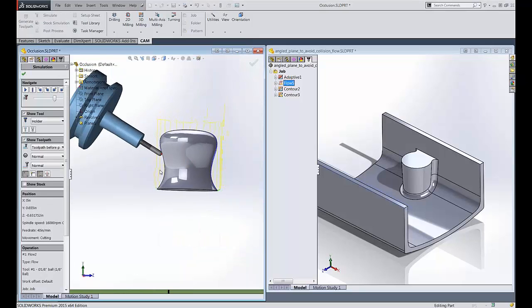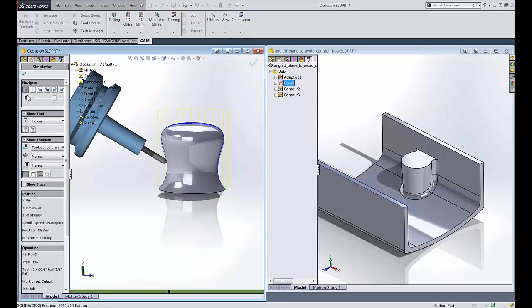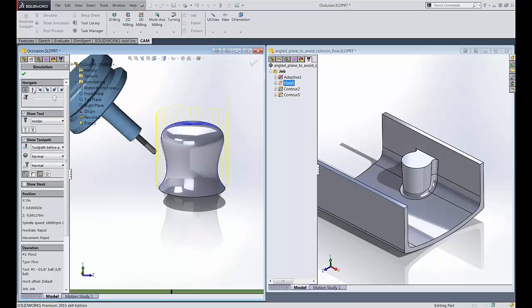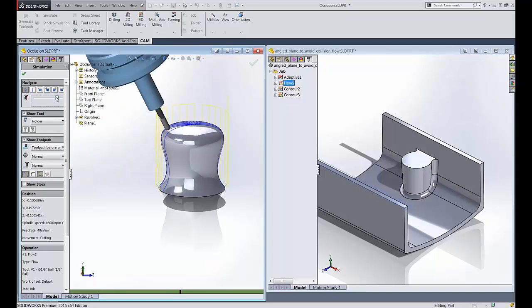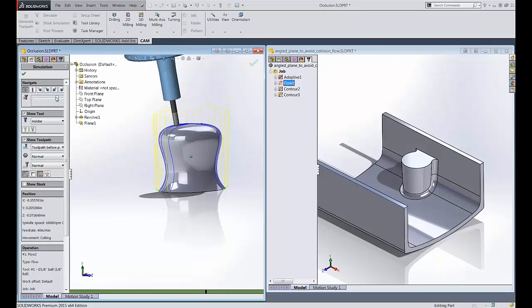Yeah, like I said, it's way more than we need. But it gets the tangency, the shank of the tool or the flute of the tool, out of the way so we can continue surfacing. And you'll see it's able to cover the entire surface with a single toolpath.